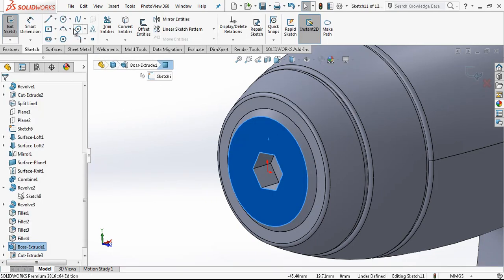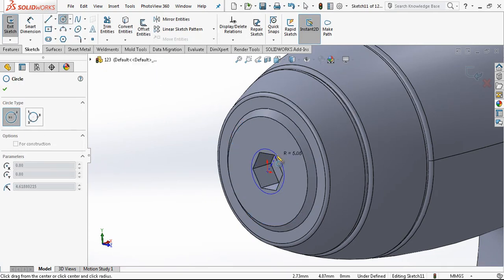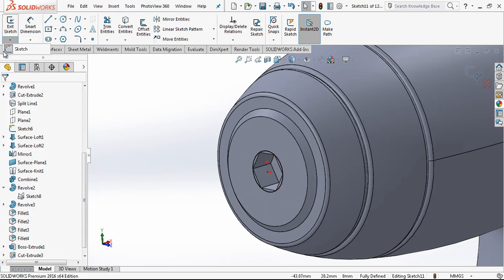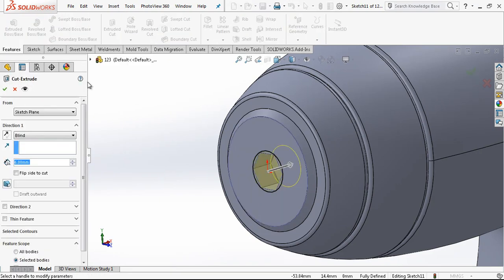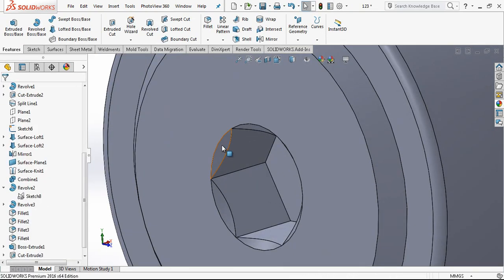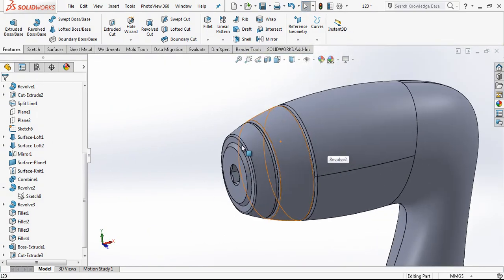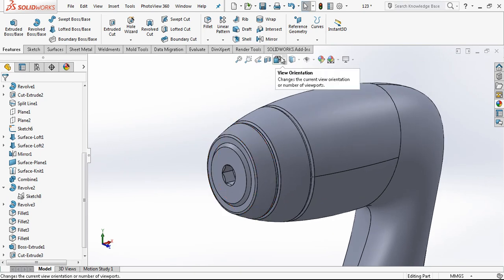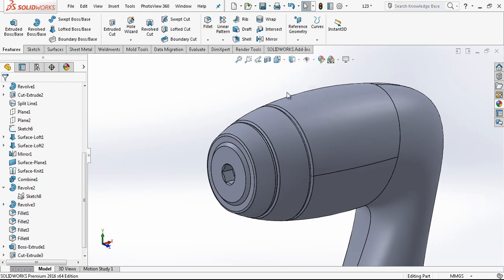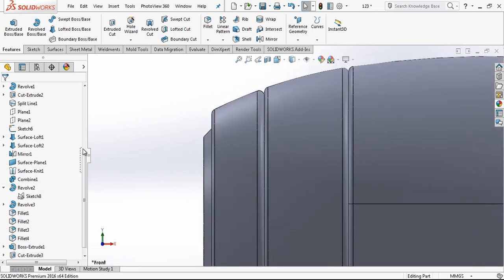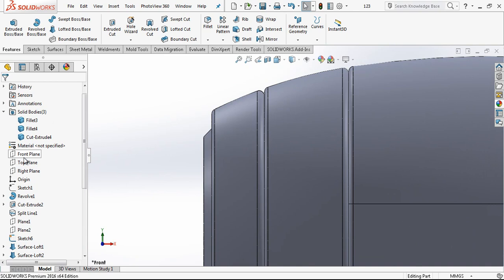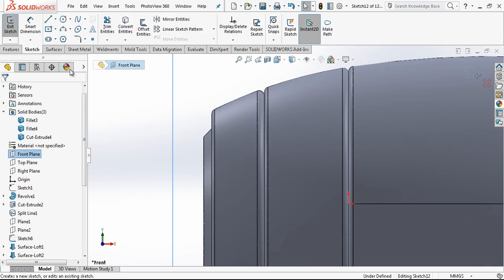And I create here a sketch and extrude cut, 45 degree cut, which creates this nice surface, and after that I'm going to create some cutout on the surface, and then we will make a circular pattern, front plane.